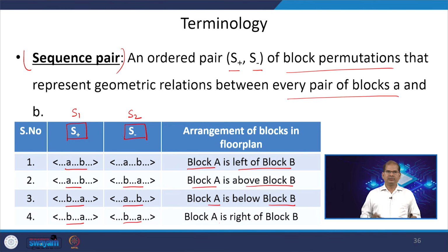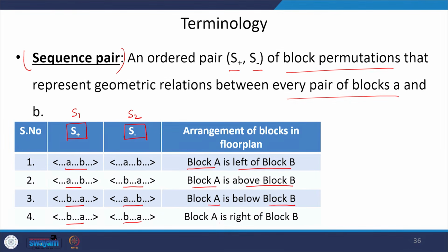This sequence pair helps me represent my floor plan in a very compact manner, which can be given as input to our floor planning algorithm. So, in this lecture we discussed floor planning, the difference between floor planning and placement, and different terminologies involving floor planning. Thank you for your attention.